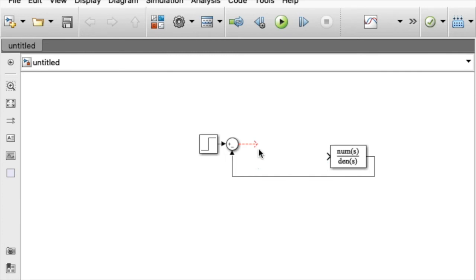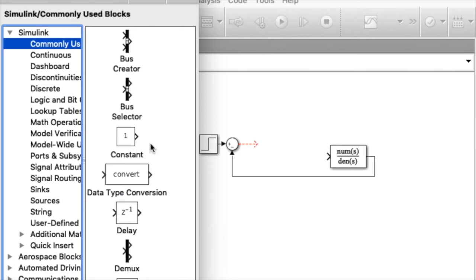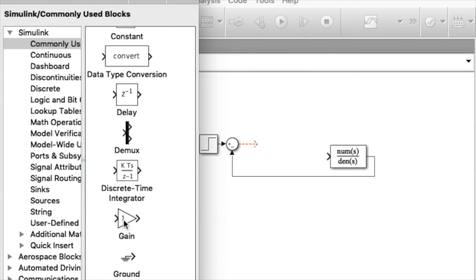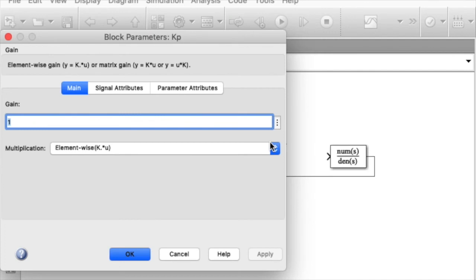So that will be then multiplied by a gain KP. So if you see where will be, so a gain, so that's our gain. We can choose our KP here. So we can write it as KP. Okay. So that's error multiplied by KP, right? So what was KP in our case? What did we choose? 11. So we can put 11 here, apply. Okay. And then,